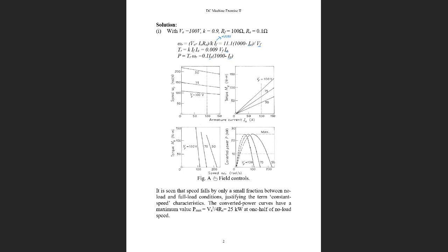Now, also from the torque-speed relationships, you look at the torque: generally speaking, as the torque increases, the motor speed decreases. This is the first one. Second one, for a higher field voltage, the motor has a relatively lower speed with bigger output torques.